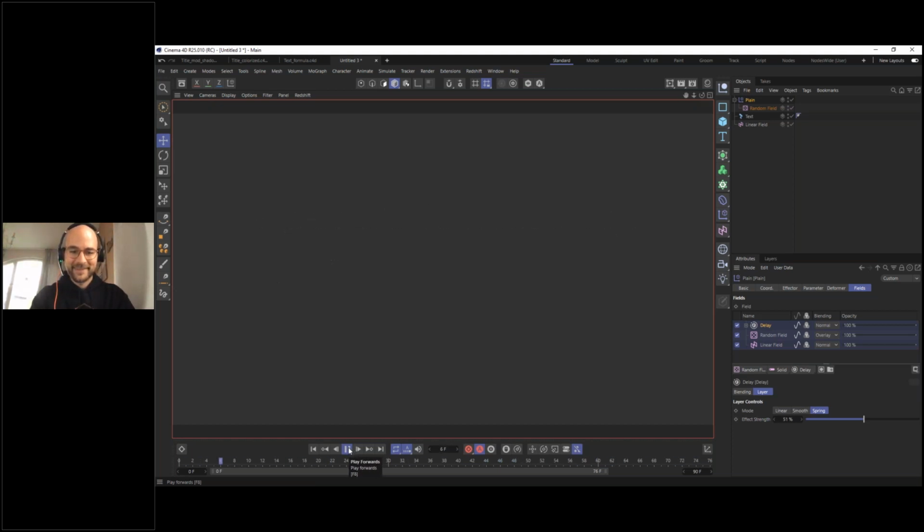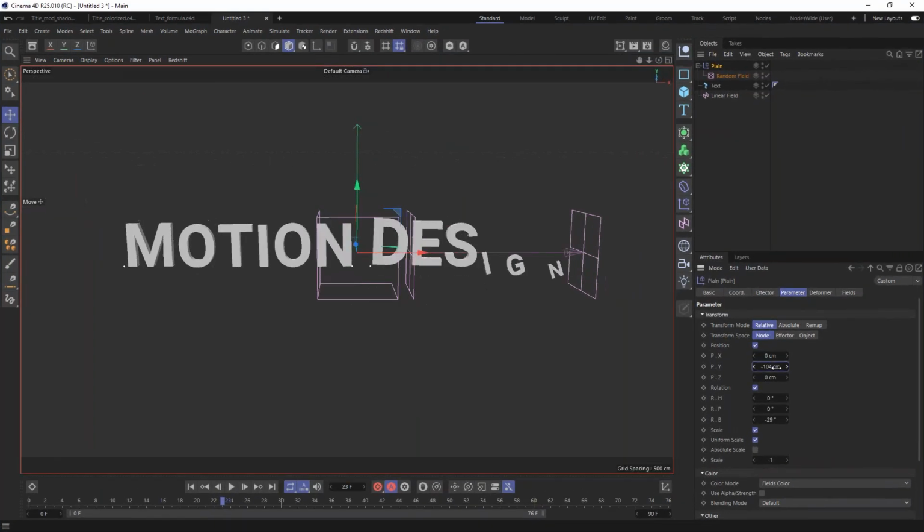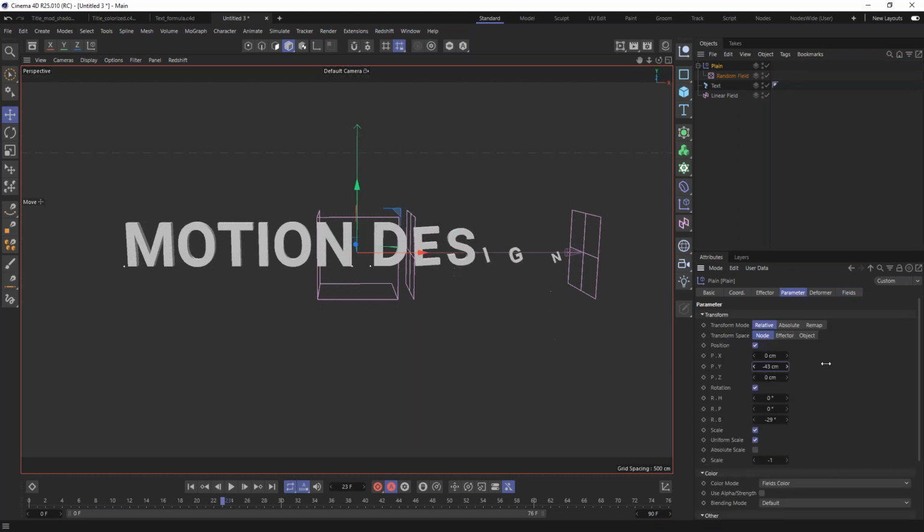Yeah, I was going to show it, but you're right to say that, because when you have the delay effector, it's almost dangerous to work with. Here, if I take my plane and change some stuff, see, it's going bonkers. It's not doing what it's supposed to do. This is not normal. This is because of the delay. So if you use the delay field or the delay effector, you really should deactivate the delay. And now if we go back to your effector and you change it, now it makes sense. So be very careful with that.